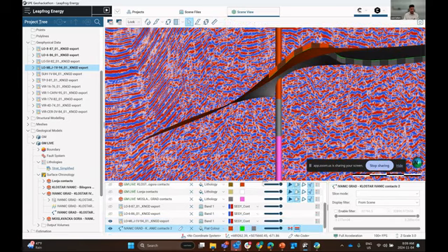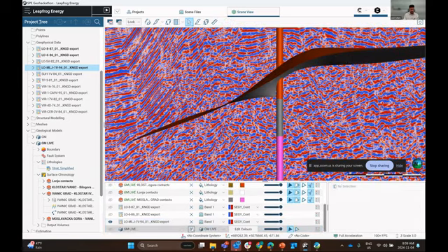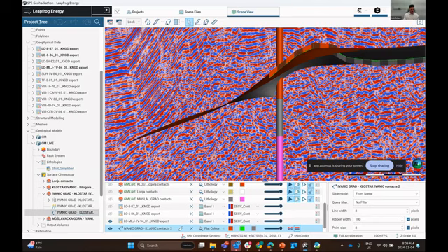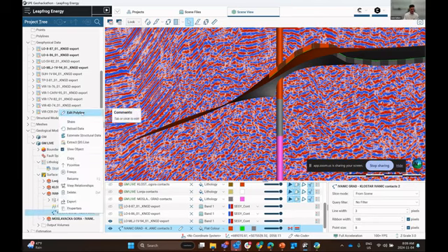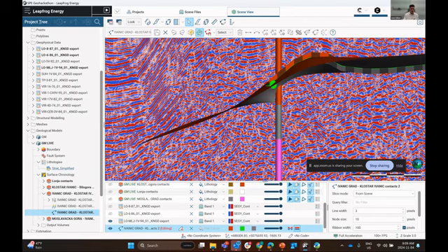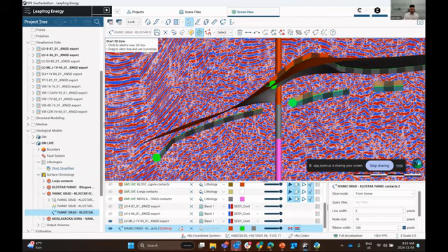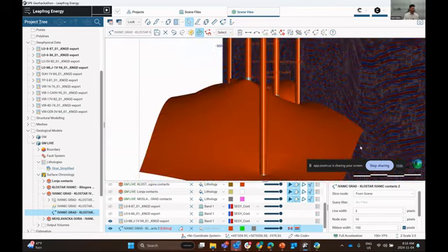So if we were to close this drawing and remove it from the 3D scene, this surface still has that polyline on it. So we can drag and drop, visualize it. We can right click this polyline and we can edit. And this allows us to continually edit this in space. So we can again activate the 3D cursor, and this is going to be a bad interpretation. Don't worry about that. And we can again continue to construct this surface in 3 dimensions.